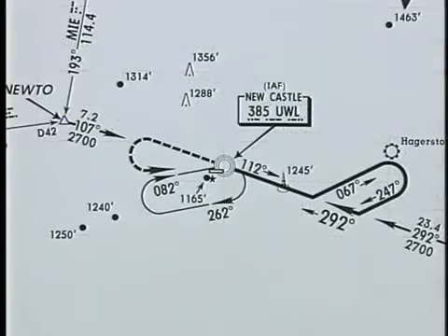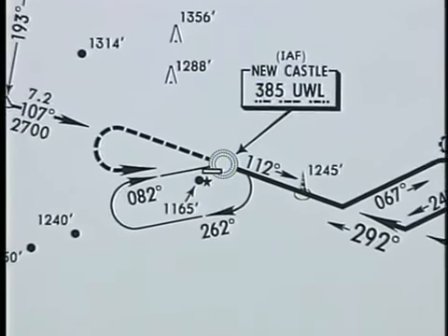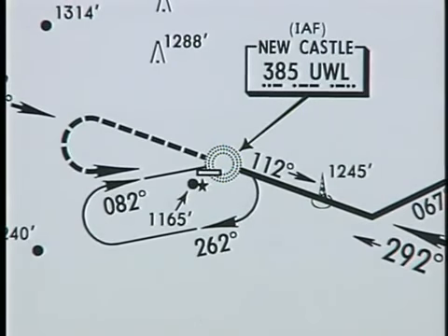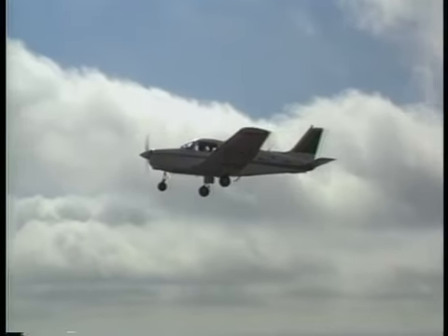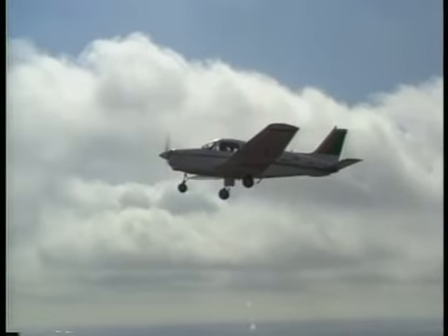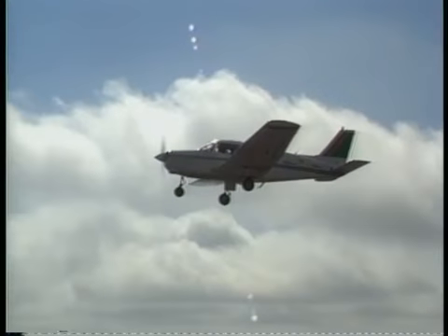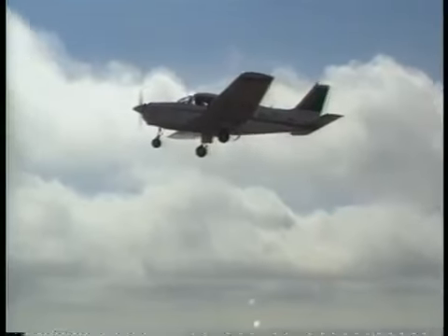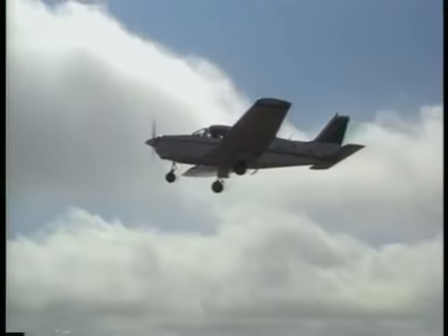As you near the missed approach point, there are many things to consider. For this particular approach, you know that the runway is left of the NDB. So, as you scan for the runway, you must consider your heading as well as the actual location of the airport in relation to the final approach course. If you enter VFR conditions, maintain a normal scan for other traffic. This is particularly important at an uncontrolled airport. In any case, don't descend below the MDA until you're in a position to make a normal approach and landing.